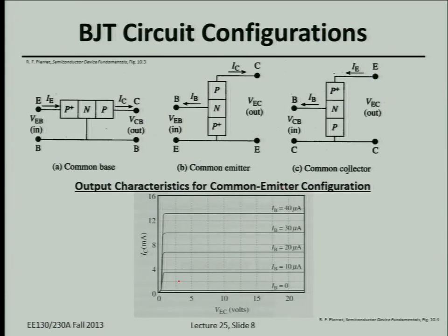Okay, so how do we use a BJT in a circuit? In this class, we'll just focus on 2 applications. One is as a switch, which is actually the last application. Again, a BJT can be used as a switch. When you turn it on, it'll conduct current and discharge the output voltage down to whatever the emitter voltage is. So it's kind of like a MOSFET. You can close a switch to pass a low voltage or a high voltage between the collector and the emitter. But actually, a BJT is used more often for an amplifier.